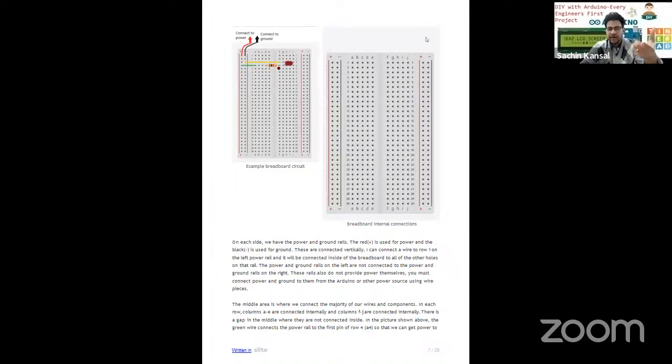You just need to purchase a breadboard. You need one LED, two wires, and one resistor, and you connect your LED cathode to negative and your LED anode to positive 5 volt. If you want to control the LED blinking, then you have to connect it to the Arduino board. Otherwise, if you just want to keep the LED running high, there is no need for Arduino at this moment. Arduino acts like a brain to our intelligent system.